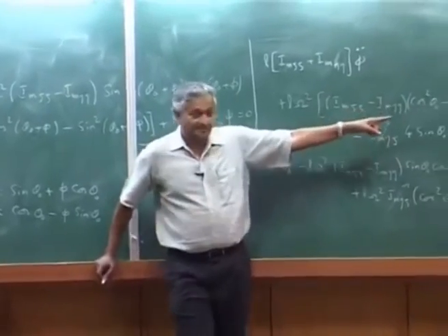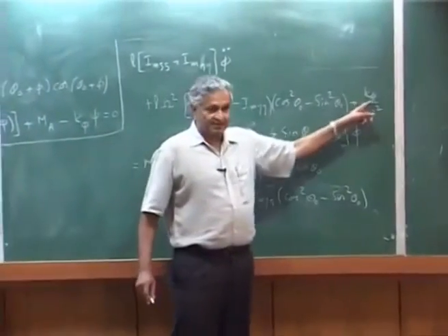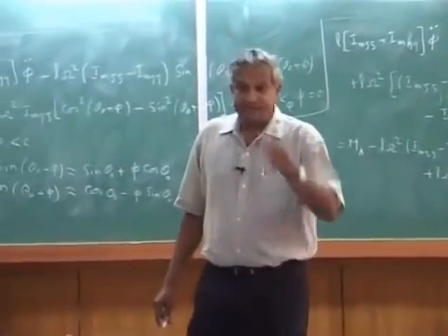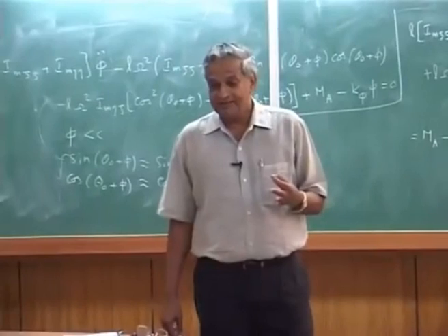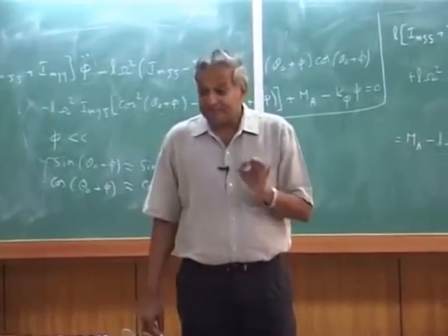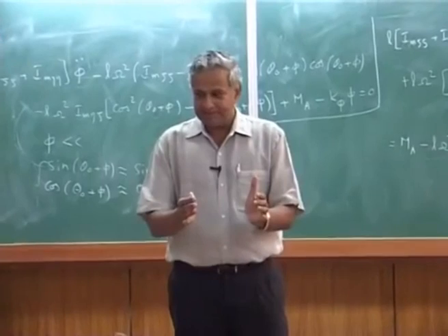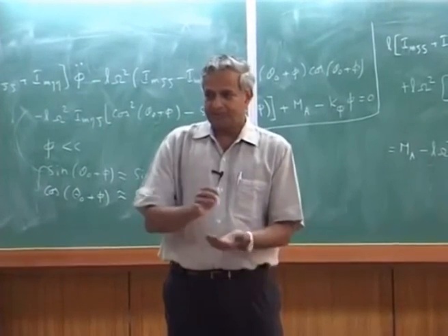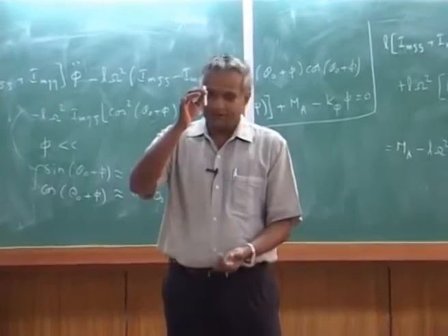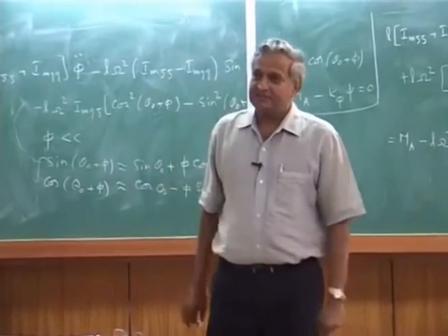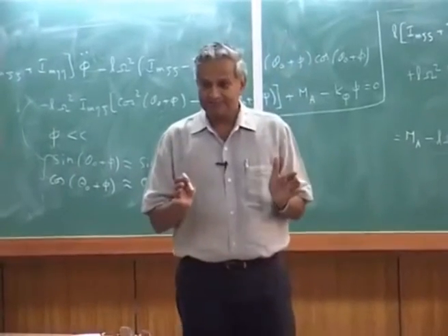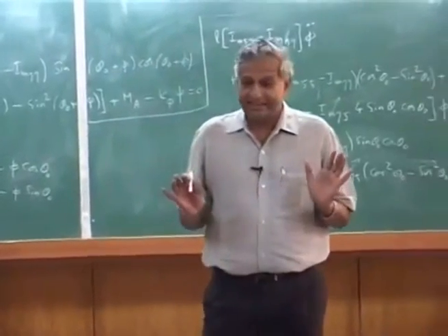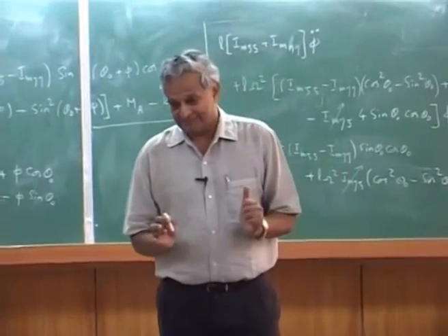That is due to the k phi. K phi plays a major role. That is why in the industry they calculate the control system stiffness. You will have the swash plate, and then there is a hydraulic jack below the swash plate, above the control rods. You calculate the stiffness of the entire unit. You do a FEM model or some approximate calculation, anything, but come up with the stiffness.